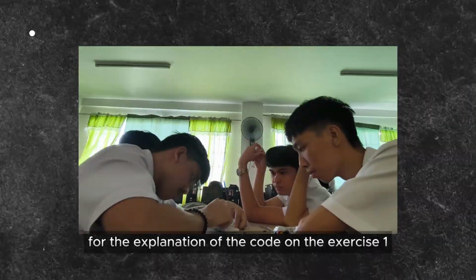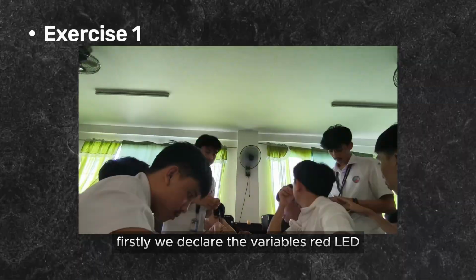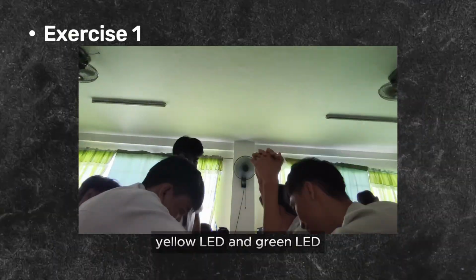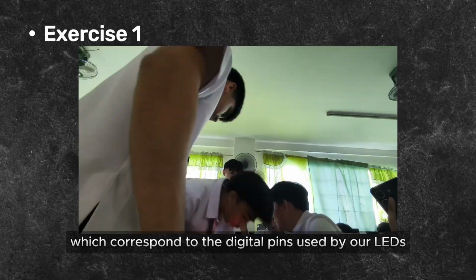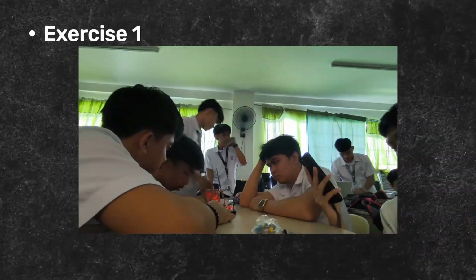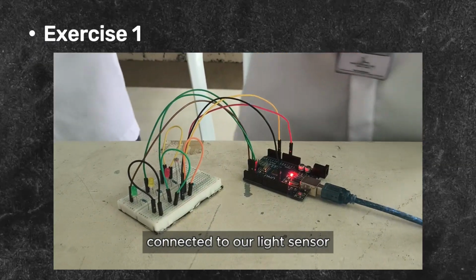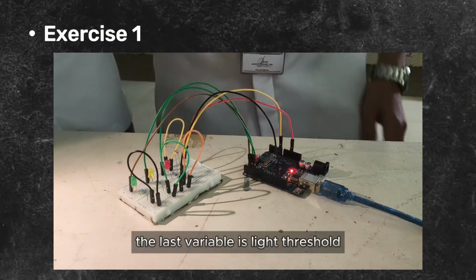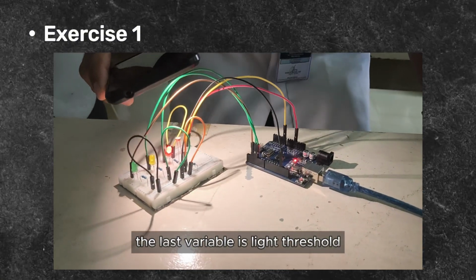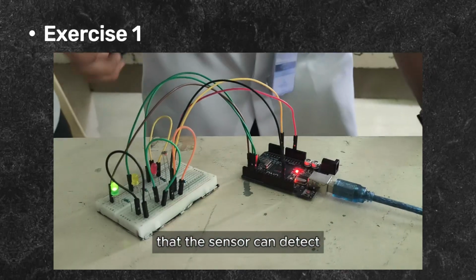For the explanation of the code on the exercise 1, firstly we declare the variables red LED, yellow LED, and green LED, which correspond to the digital pins used by our LEDs. The LDR pin is for the analog pin connected to our light sensor. The last variable is light threshold, which defines the minimum light intensity that the sensor can detect in order to